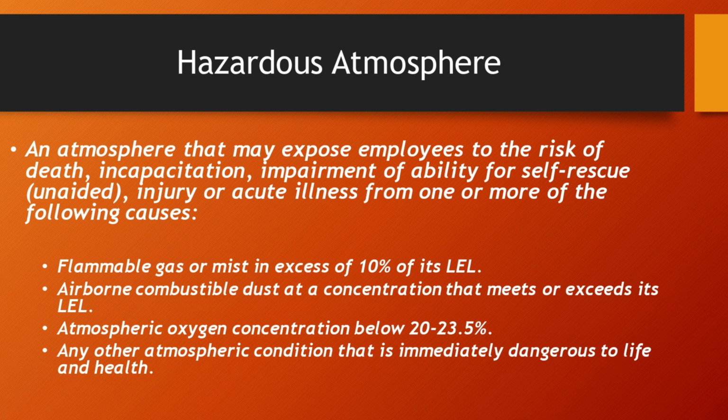Hazardous atmosphere: an atmosphere that may expose employees to the risk of death, incapacitation, impairment of ability for self-rescue, unaided injury, or acute illness from one or more of the following causes: flammable gas or mist in excess of 10% of its LEL; airborne combustible dust at a concentration that meets or exceeds its LEL.